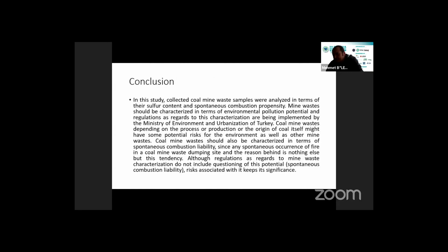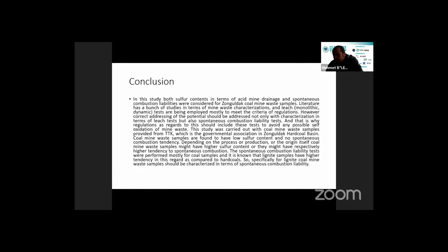In this study, we collected 26 samples and characterized them in terms of their sulfur contents and spontaneous combustion liability. And we suggest that coal mine waste, like the coal itself, should be characterized in terms of spontaneous combustion liability, and sulfur content is already being researched. These are the main topics that I would like to tell today.